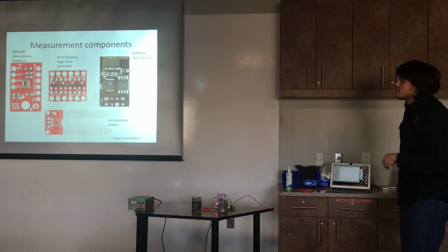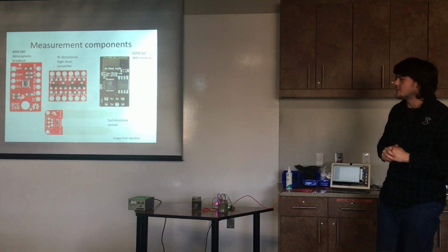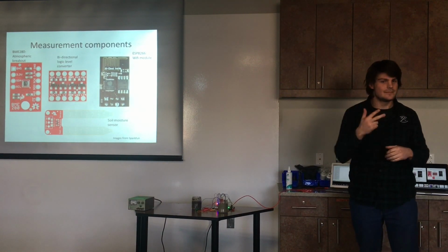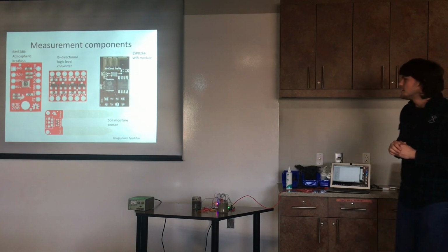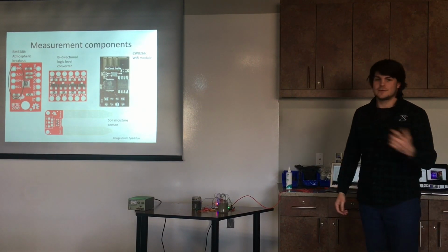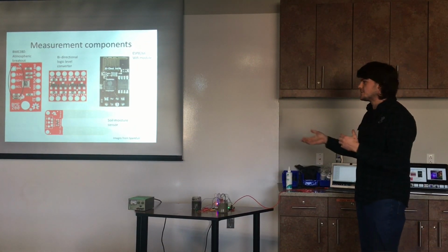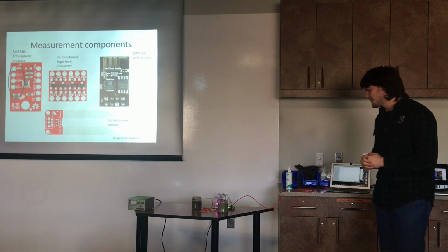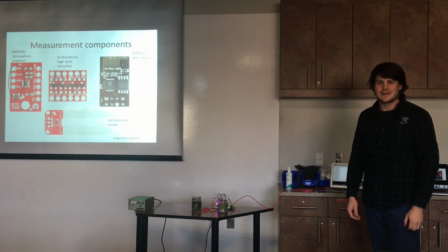So these were the components I used. On the far right is a BME280 temperature sensor. It records atmospheric pressure, temperature, humidity, and elevation, and this particular version comes with two data protocols: I2C and SPI. I decided to use I2C because it minimized the amount of wiring I had to do, because as you can see, it was quite wiring intensive anyway, and space was at a premium.